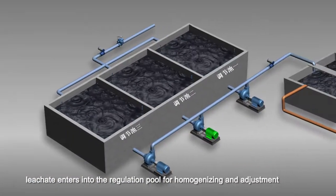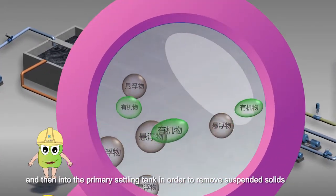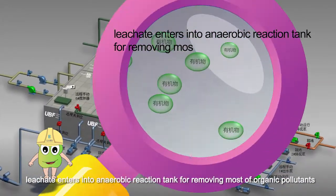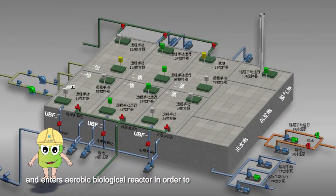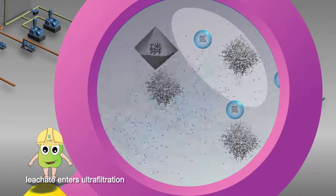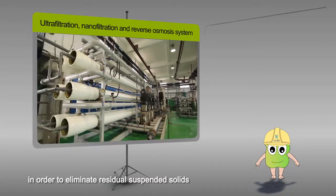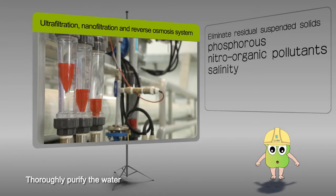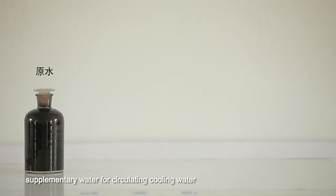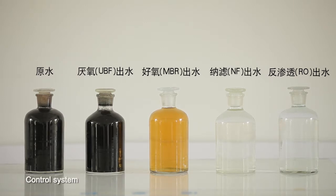In the leachate treatment station, leachate enters into the regulation pool for homogenizing and adjustment, and then into the primary settling tank in order to remove suspended solids and a small amount of organic matter. Later on, leachate enters into an anaerobic reaction tank for removing most of organic pollutants and enters the aerobic biological reactor in order to eliminate organic pollutants further. Afterwards, leachate enters ultrafiltration, nanofiltration, and reverse osmosis system in sequence in order to eliminate residual suspended solids, phosphorus, and nitro-organic pollutants. Thoroughly purify the water. The leachate after treatment is capable of serving as supplementary water for circulating cooling water, thus realizing leachate full recycling and zero discharge. 9. Control system.